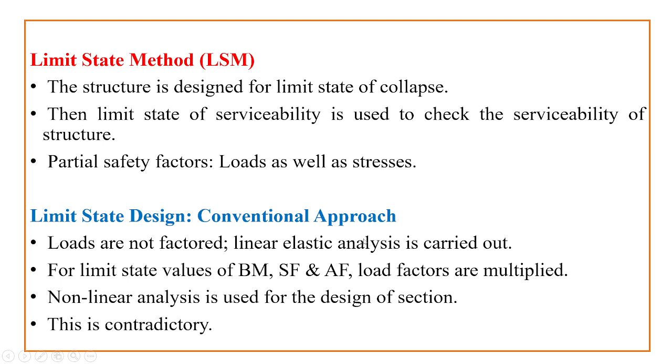But let us see why limit state design is still a conventional approach. We know that limit state method is better than working stress method, but still it is a conventional approach only. Why? Because linear elastic analysis is carried out here. However, for limit state values of bending moment, shear force and axial force, the load factors are multiplied.